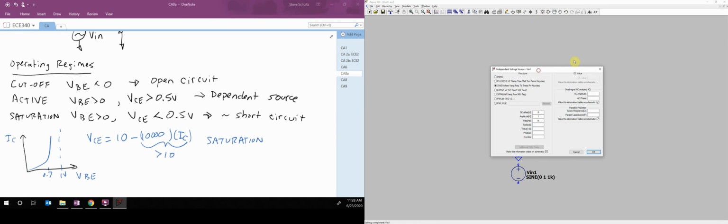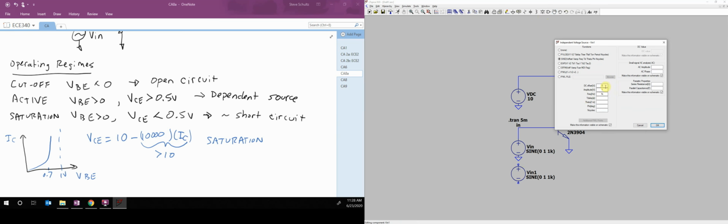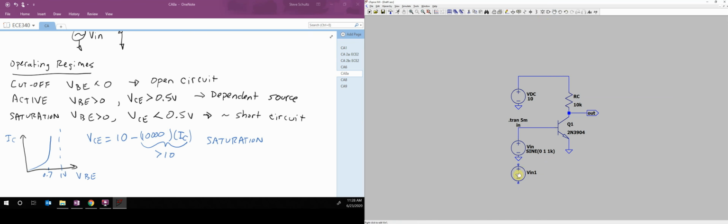And this is going from -1 to 1, so I'm going to create a 2 volt source, and call this VB for my bias. Then I'm going to move my ground down to the bottom and move this up here.